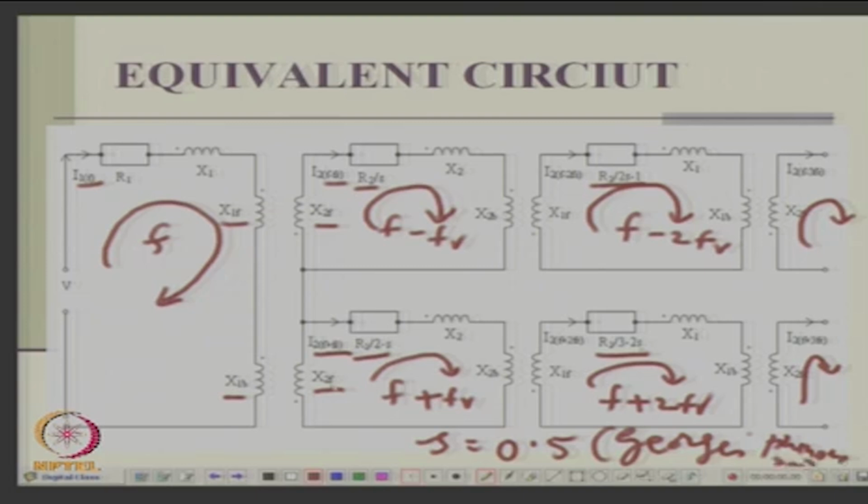Sometimes they discovered that if the stator is asymmetrical, the machine will suddenly start running at half speed. So, a machine can run at half speed if there is a DC component in the stator. Okay, this is the equivalent circuit. Of course, I have done the measurements. In fact, you can do this on one of our generalized machines in the lab. You can do a harmonic analysis. In the harmonic spectrum, you will see all these frequencies are present.